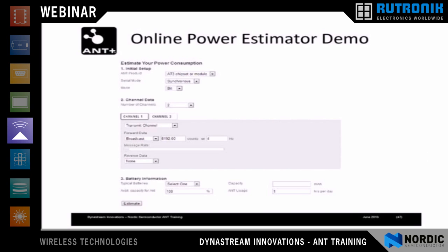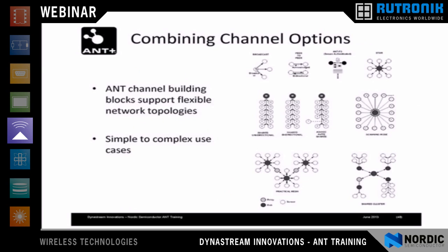So when we talk about that shared channel, for example, at 12 hertz, which makes a lot of sense for a theoretical zero latency home automation environment, you're consuming at that beacon, that temperature sensor, for example, about 241 microamps of average current. So that's 12 messages a second, 24 hours a day, and will give you about 240 days on a AA battery. So it's very, very efficient. But you can choose and measure your own power quite easily on there, and it's quite accurate.